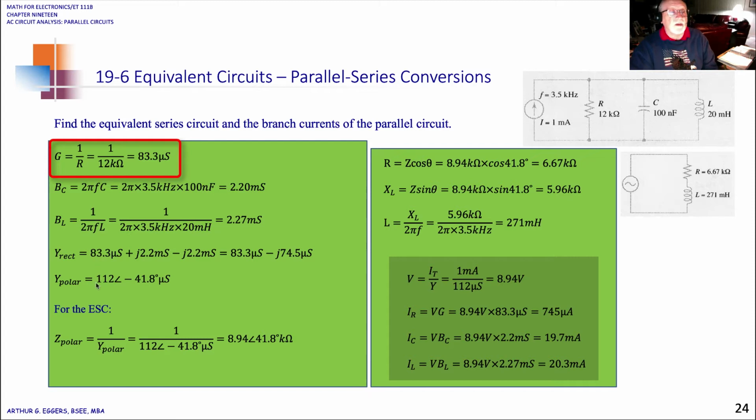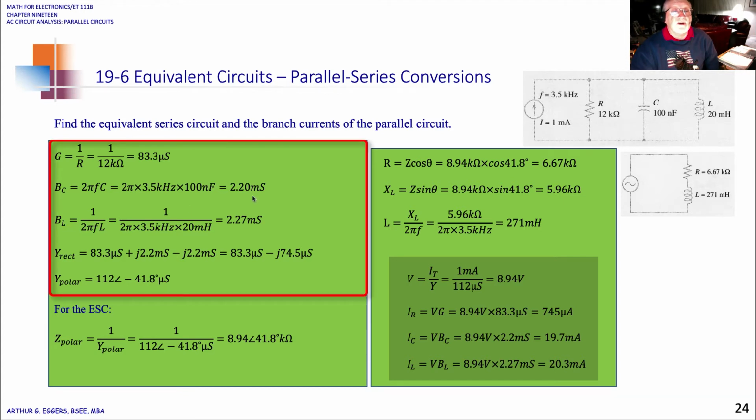They should not be a mystery to you now. We're looking at taking a parallel circuit, converting it using the reciprocal values that we learned for impedance and reactance. Now we're using conductance and susceptance. So we're calculating our susceptance both for the capacitor and the inductor. Everything then moves into Siemens.